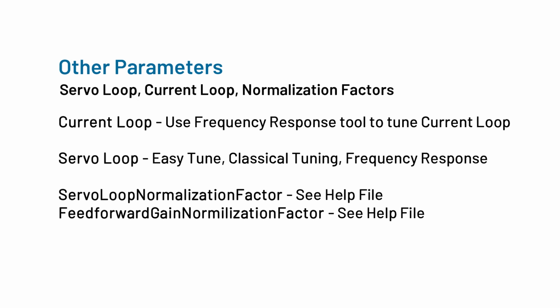Now, calculating these normalization factor parameters is going to be the hardest part. This can certainly be more involved than the other parameters and more dependent on different stage variations like direct drive linear stages, ball screw driven linear stages, or gear driven rotary stages. And those specifications on how to do each one of those are going to be a lot more in detail than we can go into this video.